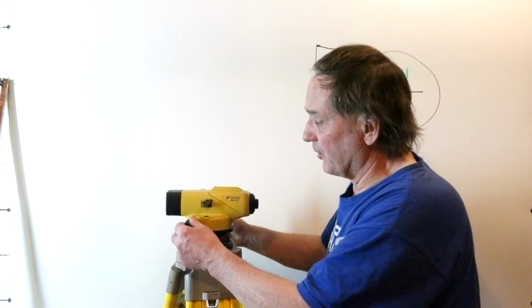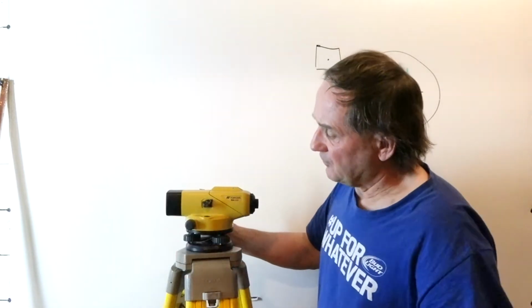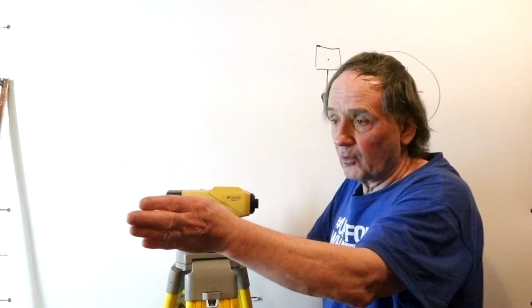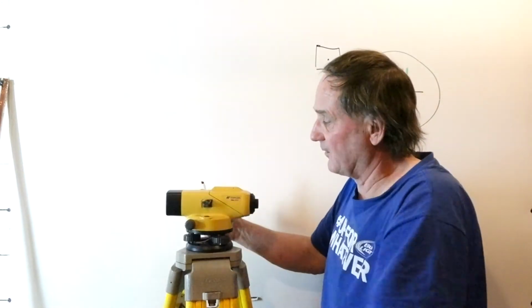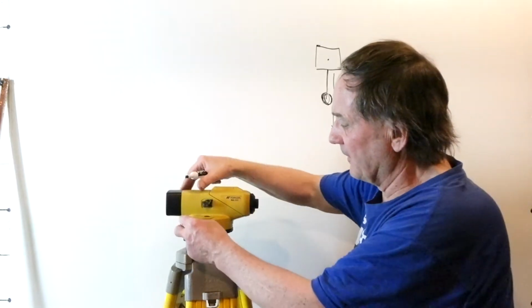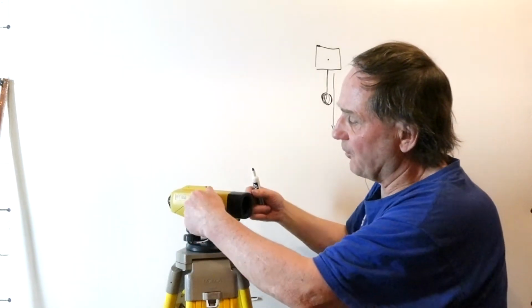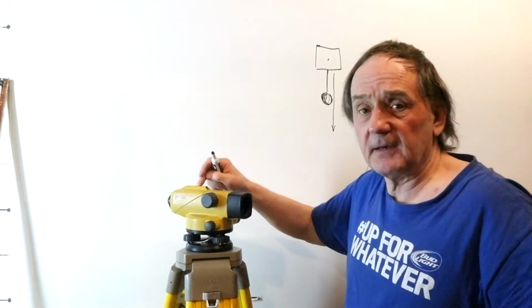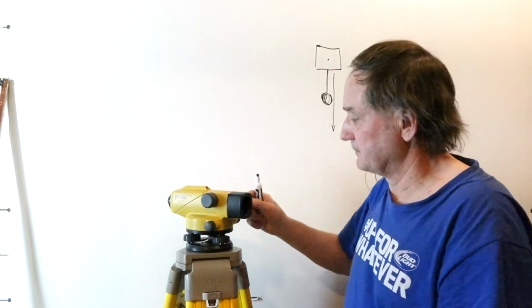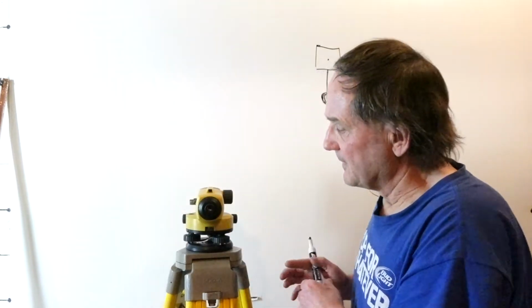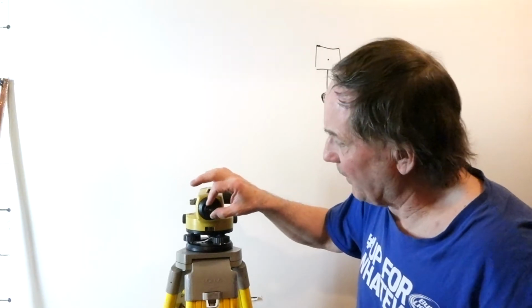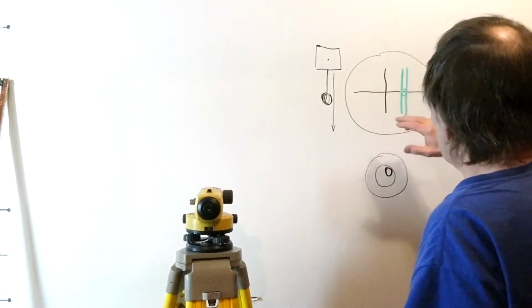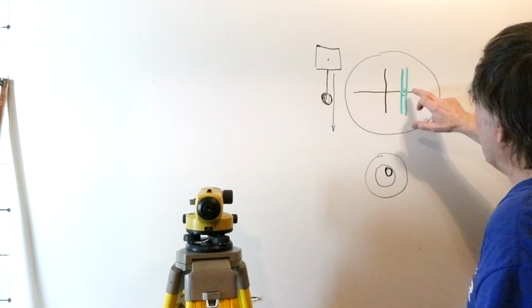You have a few controls. This is a fine control to adjust the auto level in the horizontal plane, to pan it right or left. There's a control here. This is the focus control. This happens to have a 28 power scope in it. And then sitting here you have an adjustment, and what this does, this is pretty neat, is as you adjust this control, these crosshairs will lighten or darken.